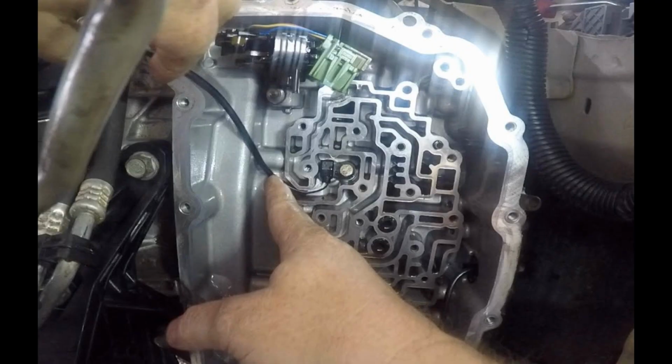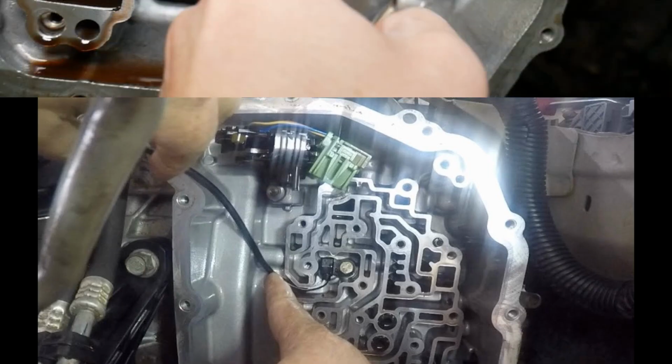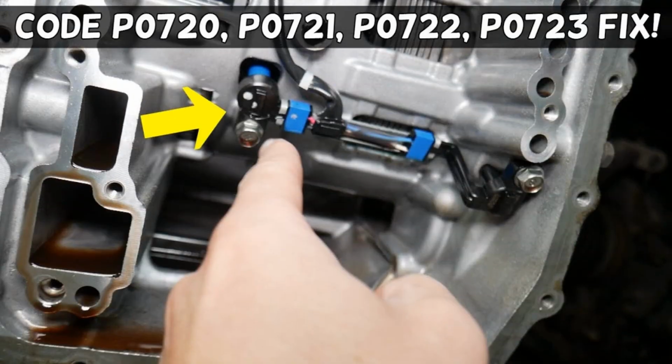If a fault is detected by the transmission control module, TCM, the PCM/ECM can override the values based on other sensors to determine the shift time. Thus, trying to adjust the torque converter and pressure if the information from the OSS sensor is not available. The OSS sensor is also normally used to display the speedometer reading, so the data it contains may not be correct.